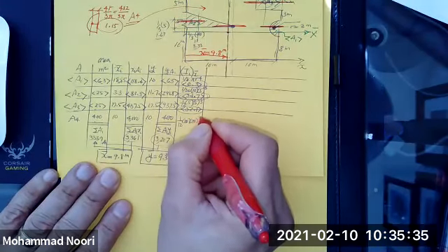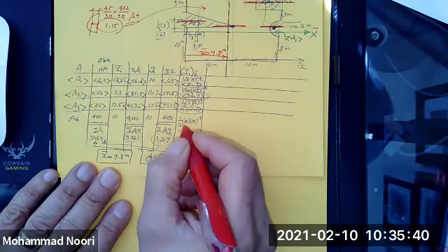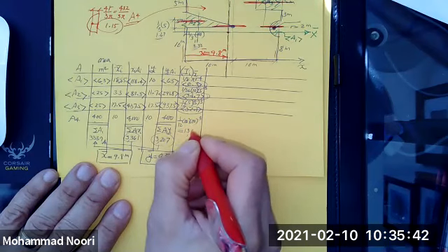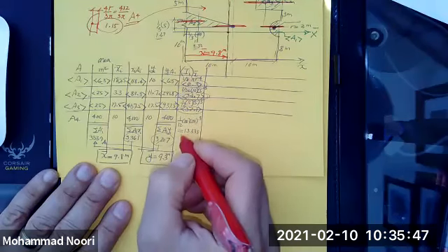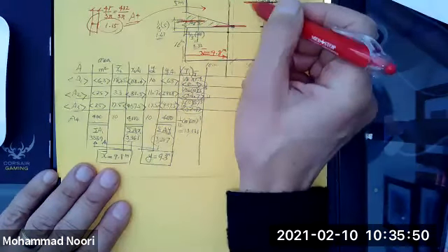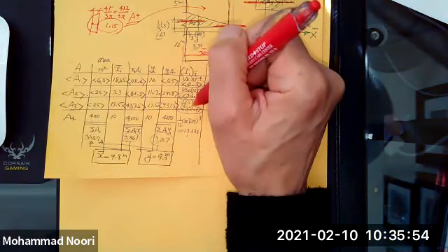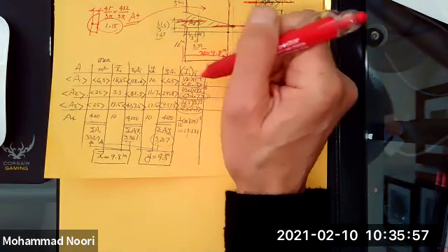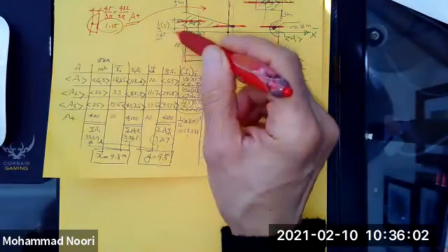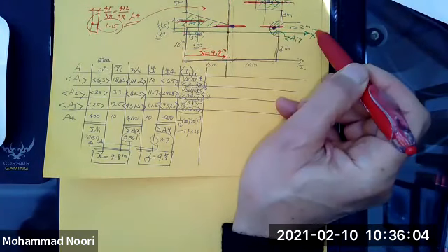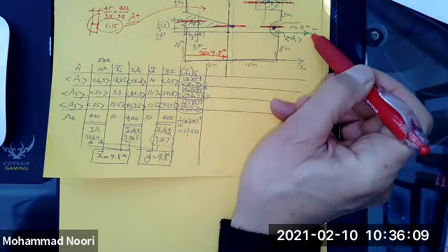Height is also 20. So that gives you 13,333. These are the moments of inertia of each shape about its own central axis. Just leave it as is. Tabulate them. That's not what we need. We need the moment of inertia of each shape about this axis, and add them up.